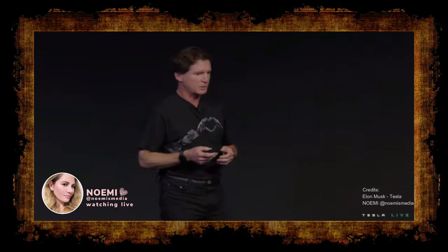Those choices, that particular choice led to a whole bunch of other choices. For example, if you want to have virtual memory, you need page tables. They take up a lot of space. We didn't have space, so no virtual memory. We also don't have interrupts. The accelerator is a bare bones, raw piece of hardware that's presented to a compiler, and the compiler is responsible for scheduling everything that happens in a deterministic way. So there's no need or even desire for interrupts in the system. We also chose to pursue model parallelism as a training methodology, which is not the typical situation.